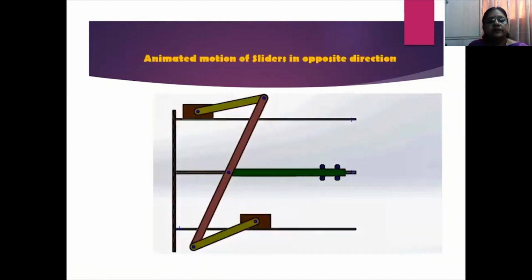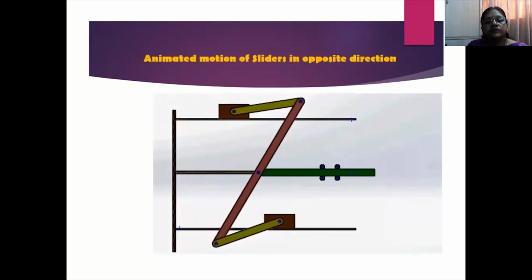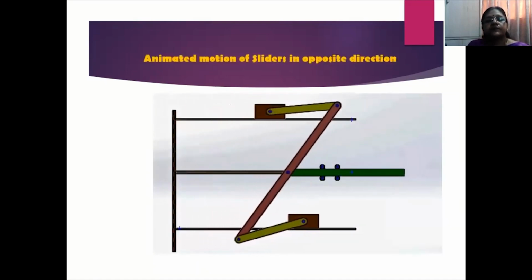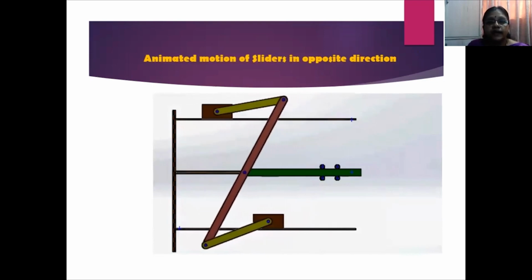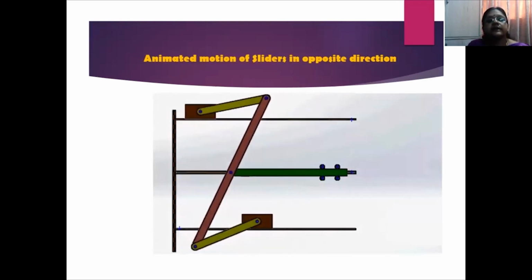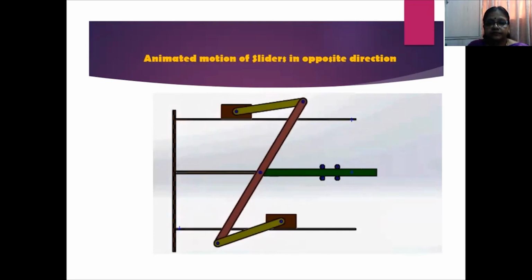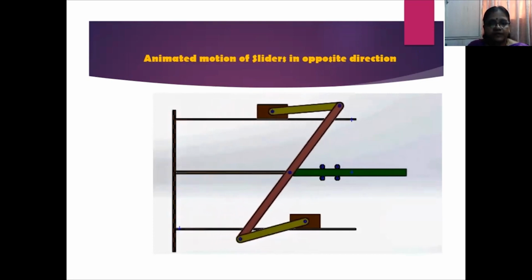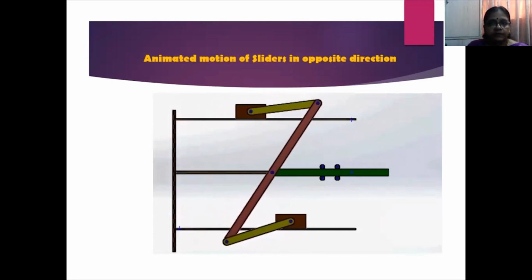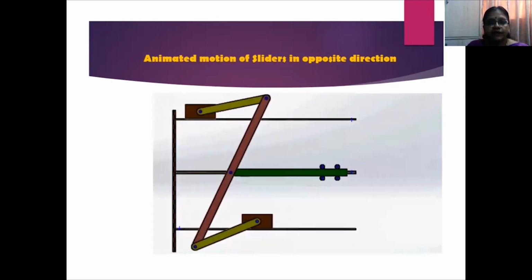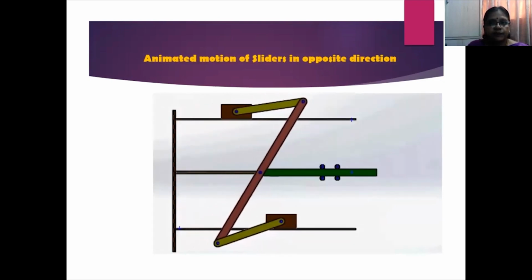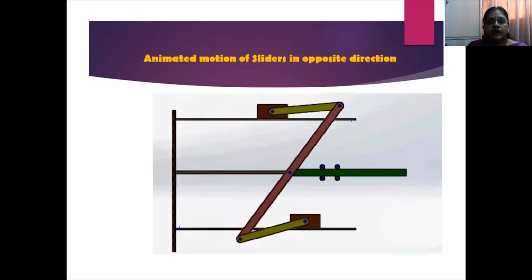Now let us see the animated motion, how this motion happens for you to get the values and compensate the error, nullify the error in both the cases. Because one becomes plus epsilon, the other becomes minus epsilon, and that gets cancelled, giving you a value of W equal to (X plus or minus Y) by 2 as an output value.